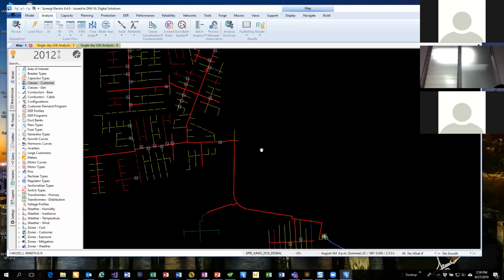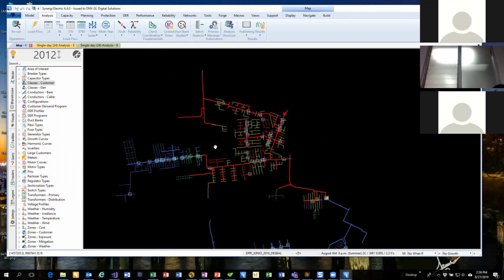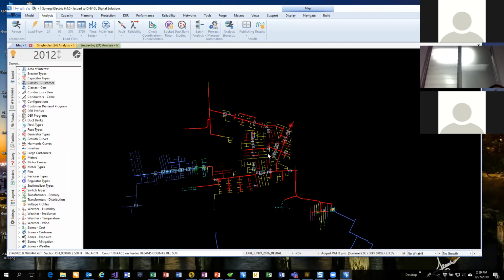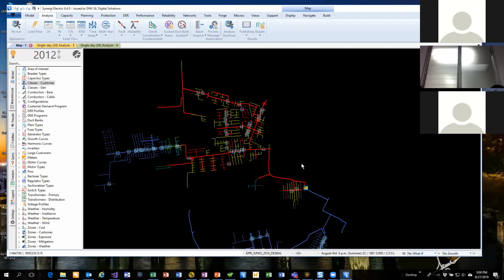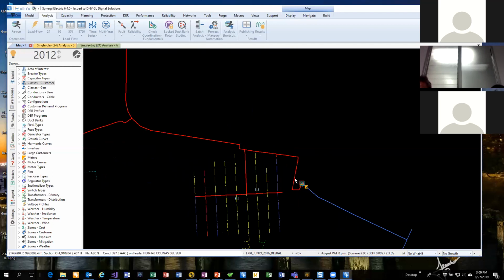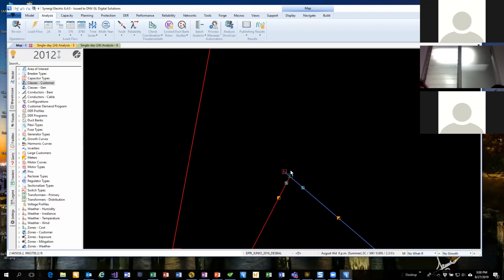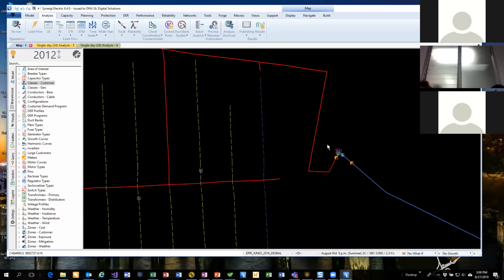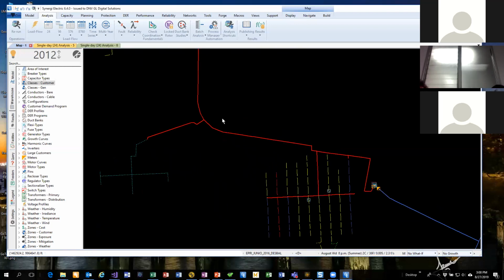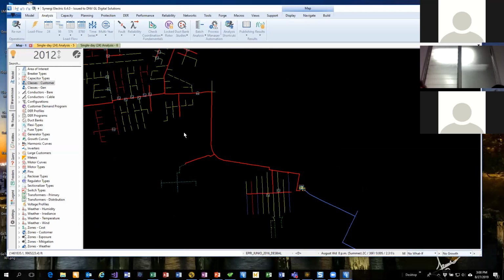So now we're able to model the PV, or I'm sorry, the loads, and that's very important. There are three things that are very important to doing DER studies, connection studies, those sorts of things. One is some sort of time-varying load model. The second one is the solar generation model. And the third one is a substation. I noticed you don't have substations on these feeders. We could talk about that later, but there are different ways to get a substation built into these.